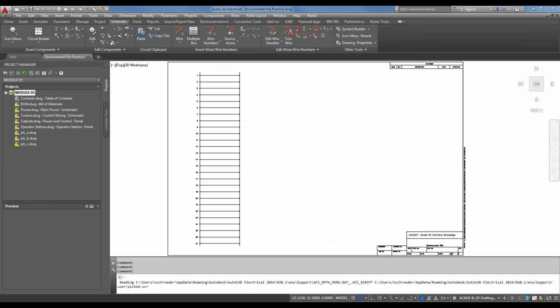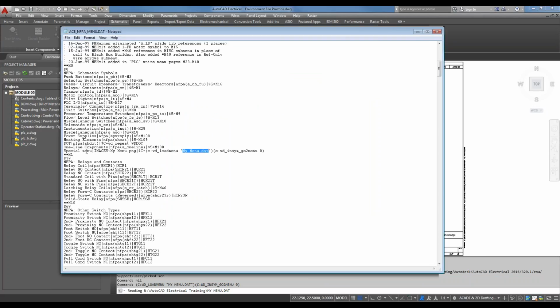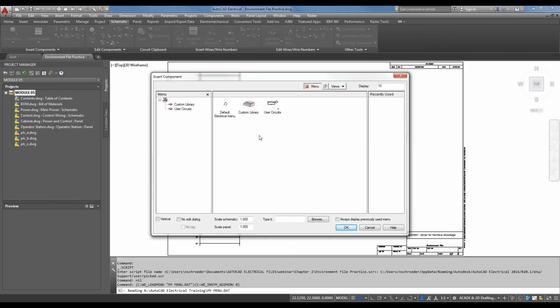So if I click on this, this will call up my special menu, and what this allows me to do is I can actually just add that one line into each user's computer, and that allows me to connect them with this custom menu at any location just by simply adding that one line to their standard menu, the special menu, images.menu.png, and then this command prompt here to load that special menu file. So you need to put all of this in here, separated by the vertical spacers here, and that will allow you to call up your special menu.